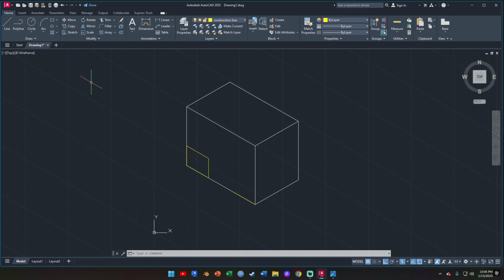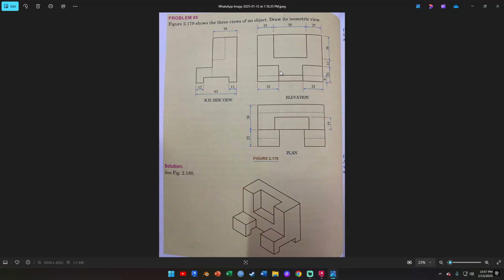So next rectangle now, click on line again, and you basically repeat the same thing. You go up 25 mm, and this side you come back 32 mm, and then you close off the shape here. And as always, if you want to stop drawing the line, you press your escape key. So we have these two rectangles here. We need the 9 mm line here, right?